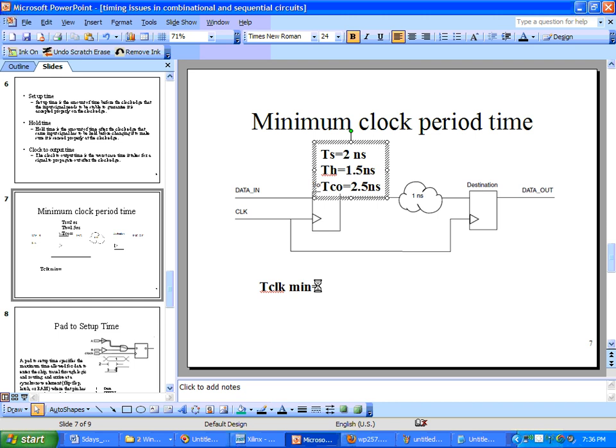Okay. Come on, let us take an example that at 10 nanoseconds a clock edge has come on this one. The next clock edge, how early can it come? That is what we want to analyze. Late means if you want to trigger after 1 millisecond, there is no problem. But how early you can trigger is actually important, because if you can give the clock triggerings quickly, the circuit will be faster.